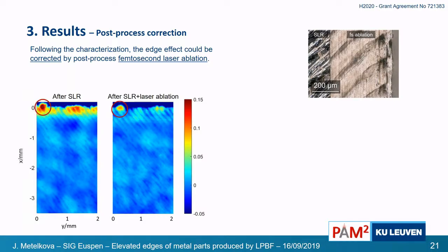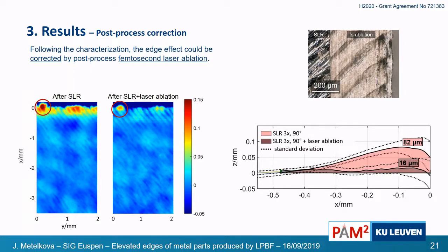However, if you have some larger particle accumulations there, of course, in our case, we use femtosecond laser ablation, and this is a cold process, so there's no melting. So, of course, you will still have this high deviation around the edges in case you have this kind of feature. However, we could reduce the maximum height quite significantly. Of course, it could be reduced even further, but by then the method was not fully developed, so it can be even closer to the zero line.